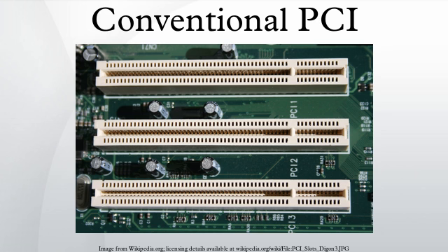Type II cards have RJ11 and RJ45 mounted connectors. These cards must be located at the edge of the computer or docking station so that the RJ11 and RJ45 ports can be mounted for external access. Mini PCI is distinct from 144-pin micro PCI.